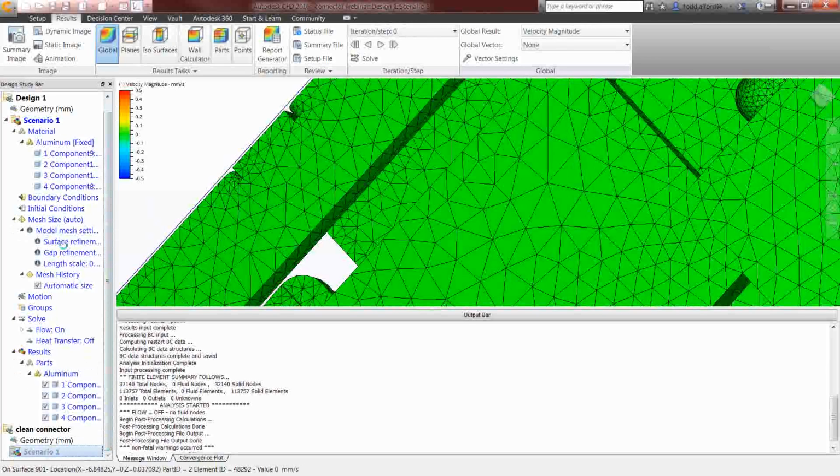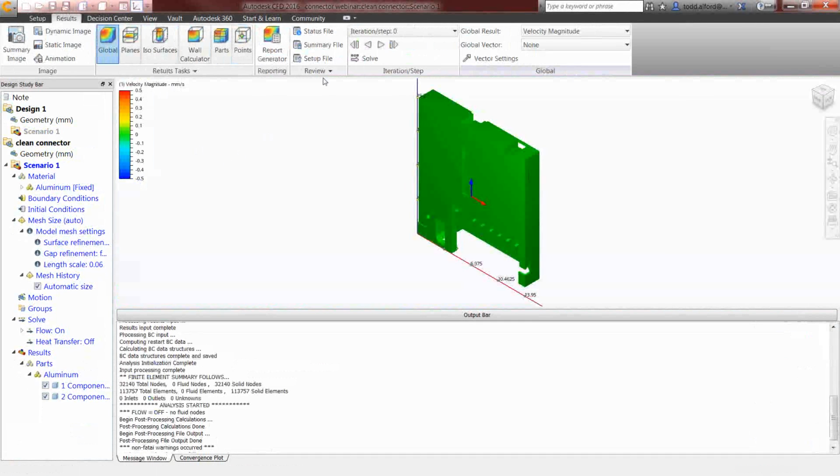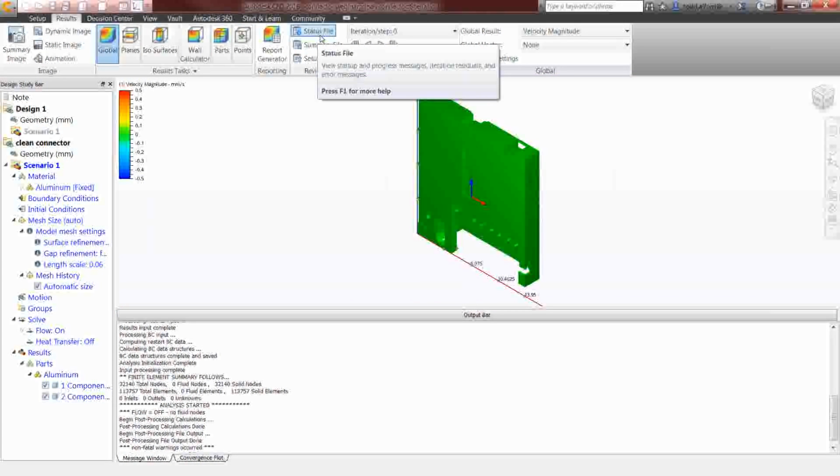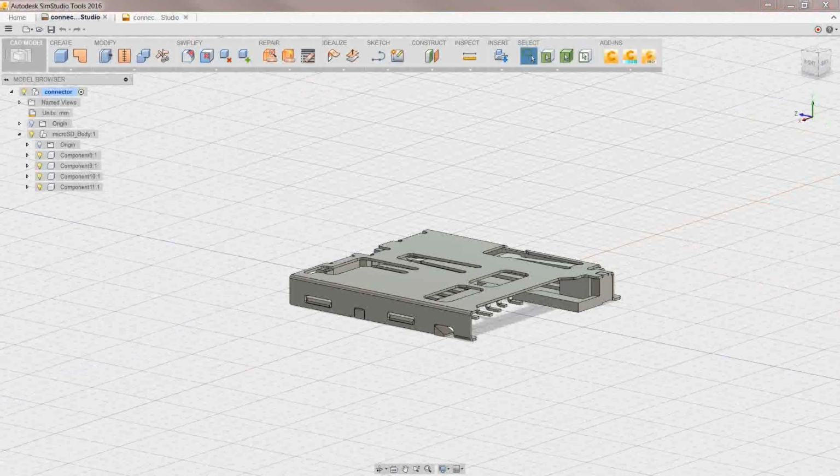No, that's cool. The only other thing I would tell the audience is that when we're in the assessment, I would very liberally go and change the definitive number that points out the sizing information in the model assessment toolkit, which flags possible or potential problem areas. So if it says 0.003 millimeters, for instance, as the threshold, and you know that you don't care about any edges that are over 0.002 meters, and anything under that you really care about, change that threshold if you want.